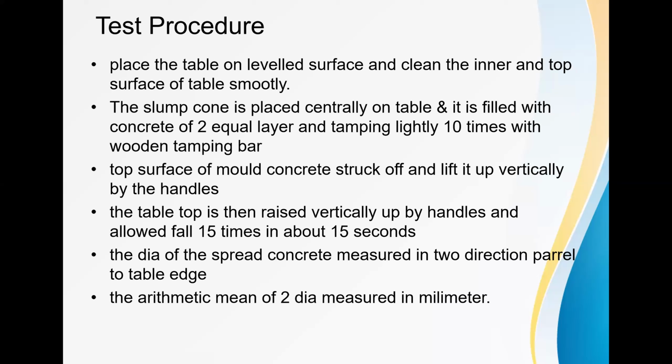The diameter of the spread concrete is measured in 2 directions, parallel to the table edge. The arithmetic mean of the 2 diameters is then considered, in millimeters.